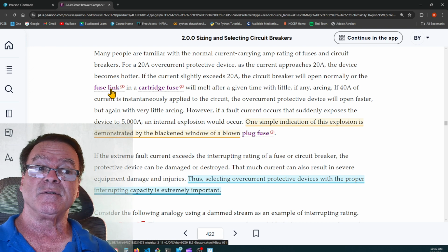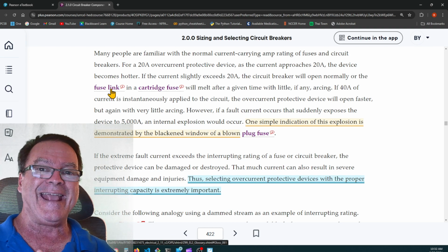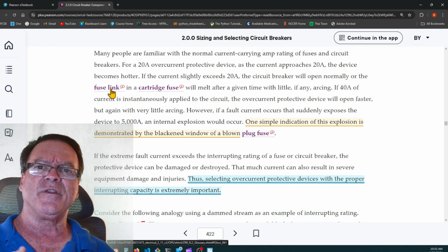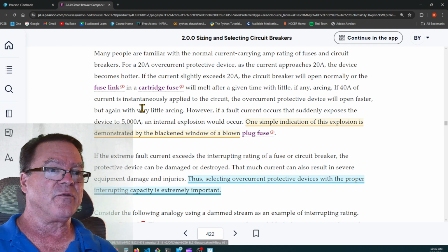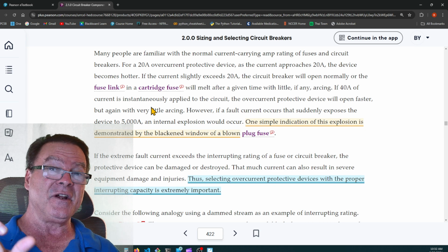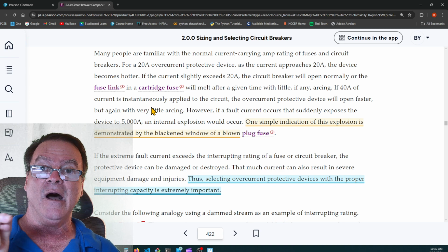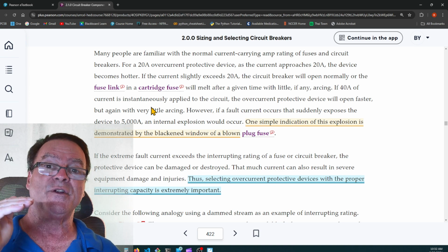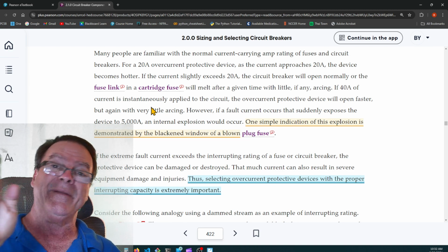Below 20 amps, it has to offer very little resistance to the circuit. In other words, at below 20 amps, it cannot heat up to a point of having a resistance that will in any way interfere with the working capacity of the circuit itself. That's why I say they're remarkable. It's amazing to me that they are a conductor for all intents and purposes. They are a conductor until you reach their rating capacity. When you reach their rating capacity, now they start to function as a fuse, and they will melt.